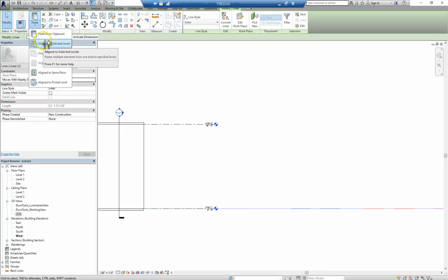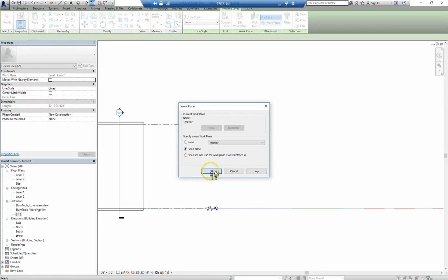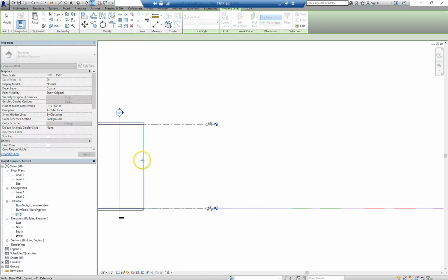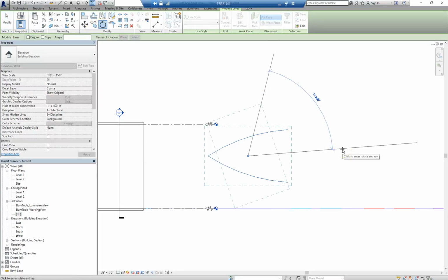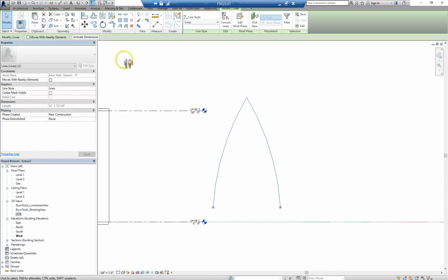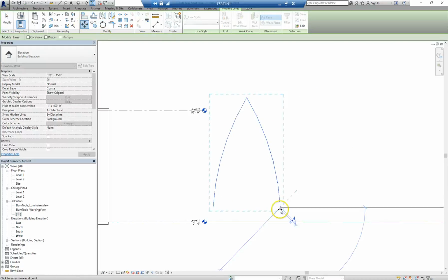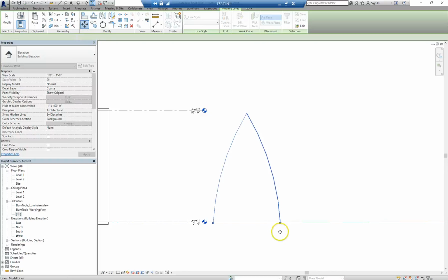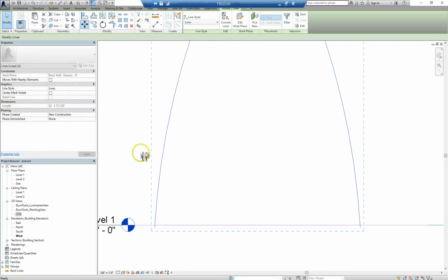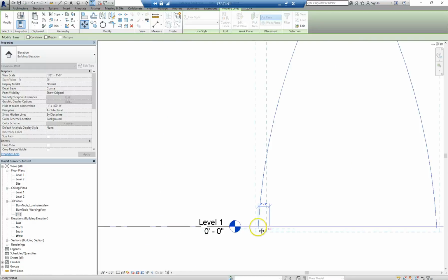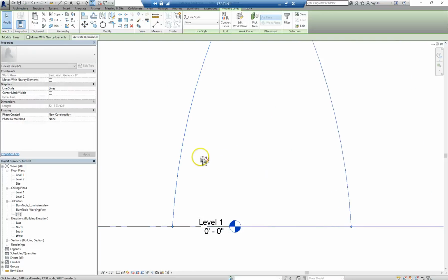Or just paste a line to selected views. I'm picking a plane right here. I'm picking the back of that existing building, so that's a starting point. And I'm just going to rotate this into place and get it to line up with the bottom of the level. This takes a couple tries because I miss. There's a miss. Let's do this again. Try and get this something I can click it to. Hit Tab until it clicks on the line. There you go.